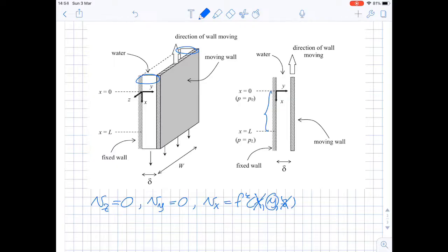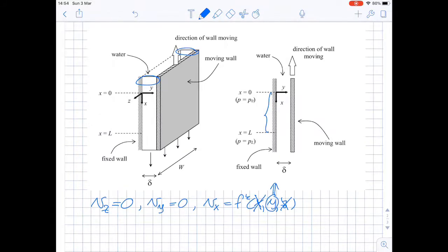Once we analyze something like this, we always say that whenever we have velocity as a function of a variable, in this case y, the shell is supposed to be thin in this direction. So my shell is supposed to have the thickness of delta y. In the x direction, it's supposed to be full size because it is not a function of x.